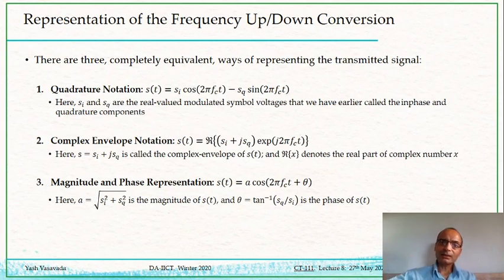And then that selected sample we will send to our maximum likelihood detector based on the decision region, and it will decide which of capital M possible symbols at the transmitter side was actually transmitted. And then once that decision is made, the symbol to bits mapping table will be implemented at the receiver, which will convert that detected symbol into small k number of bits. And so you get the bits back at the output of the demodulator.